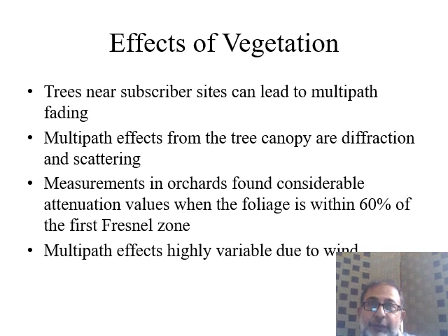As both the transmitter and the receiver antennas move away from each other, the earth bulge comes closer to the center point of the line of sight, basically. And if it enters into the 60% of the Fresnel zone, the communication is hampered drastically.